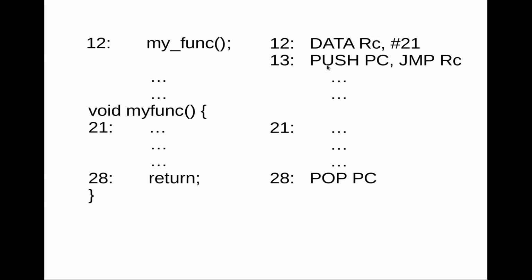And then subsequently, we'll simply add some microcode to the push instruction when we are pushing the program counter. And so if we ever push the value of the program counter onto the stack, there'll be an extra bit of microcode there, which will simply read out the value which is in the C register and then put that as the new value into the program counter. And so by doing that, we will in fact at this point have stored, in this case 14, which is the continuation of this function after the function call, onto the stack.